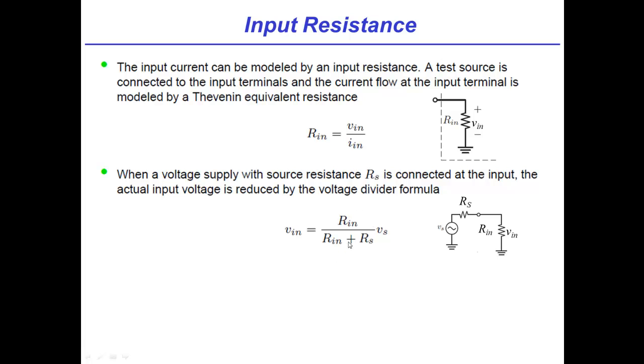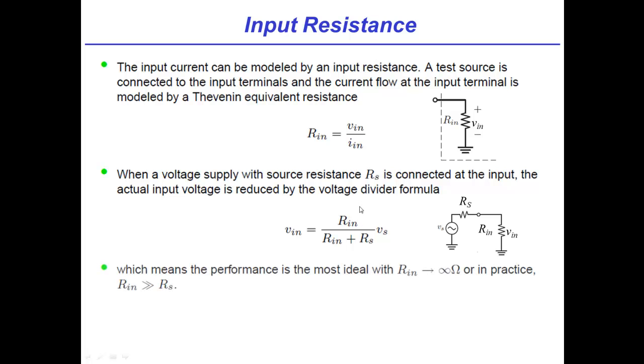Right. So our goal is generally to make Rin be as large as possible. In an ideal world, it should tend towards infinity, but in practice what we're saying is we want Rin to be much, much larger than Rs. And these numbers in real amplifiers are pretty humongous, right, Vivek? That's right. It turns out this is not really a big limitation in modern amplifiers. In modern amplifiers, Rin can approach a teraohm. Wow. So it can be really large.